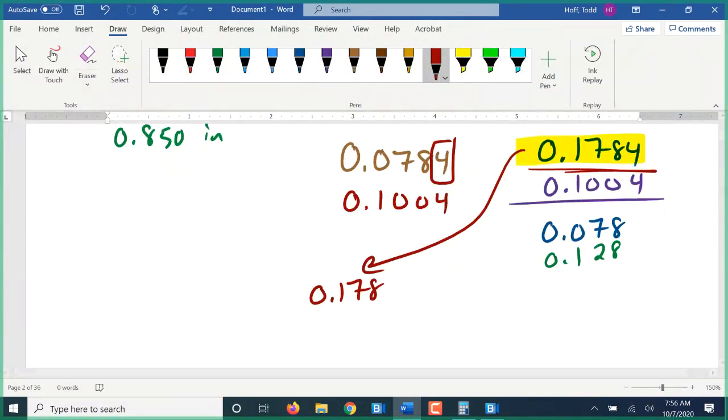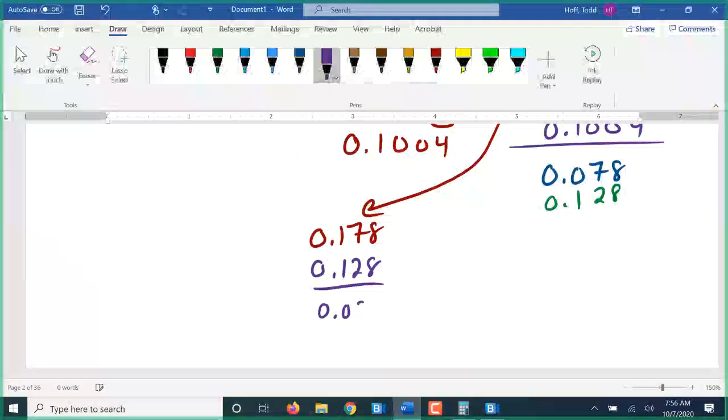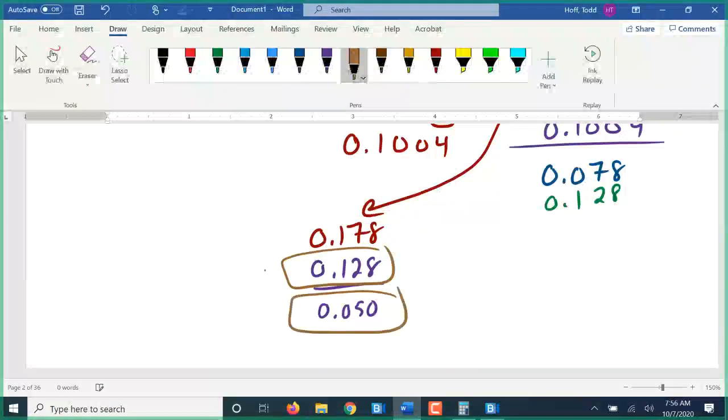Now from there, I can build it because I can put in 128, which brings it down to 50. And so I could use the 128 out of the 49 block series and the 50 out of the 9 block series. So there are limitations to these gauge blocks. Even though they are very versatile, there are some limitations.